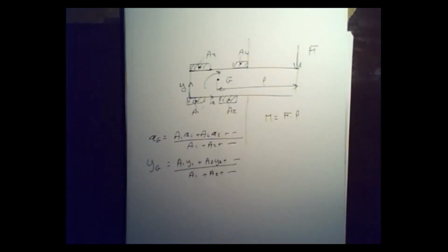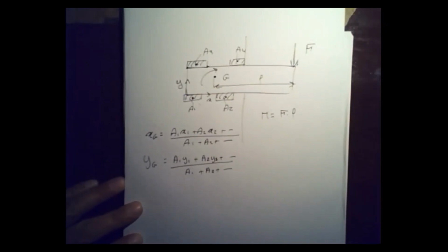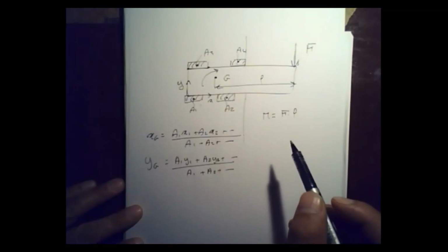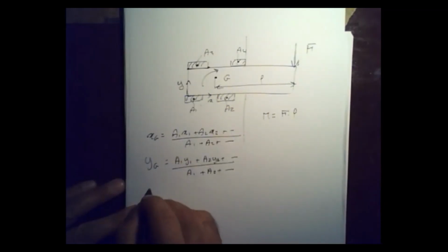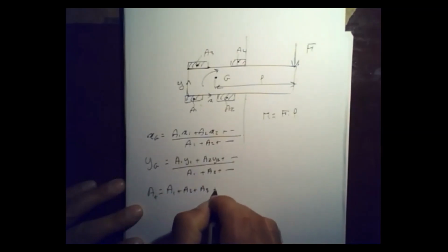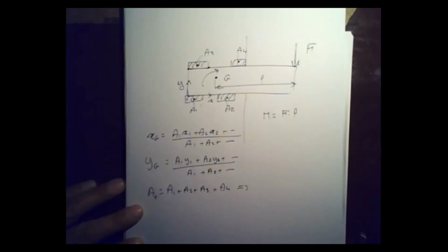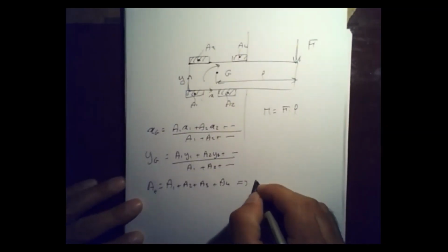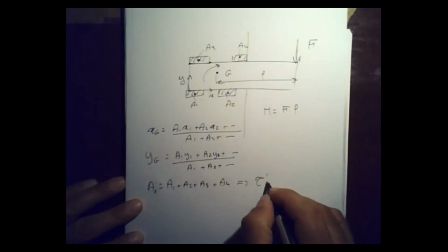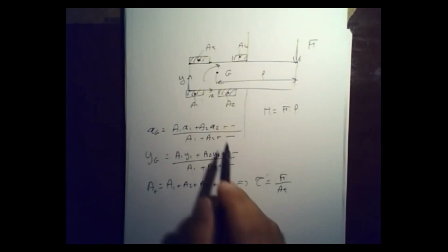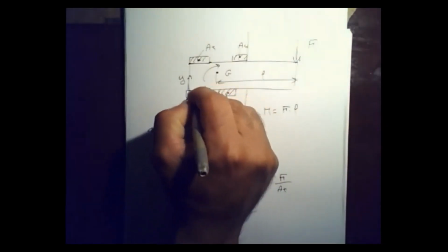And the loads that we are going to have applied over here is a single shear applied everywhere on the weld, right? And the total area of this is obviously going to be equal to, let's say, A1 plus A2 plus A3 plus A4. And just like what we said earlier, you're going to have primary and then secondary shearing. The primary shearing is caused by the shear force F over A total, right? And then the net shear stress is going to be everywhere, on every element.